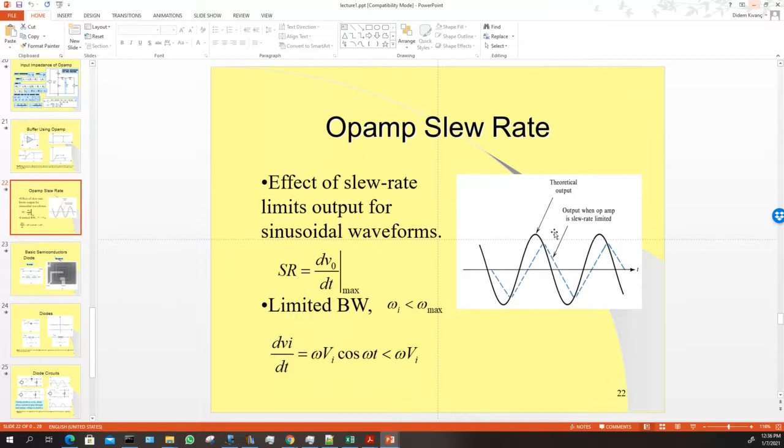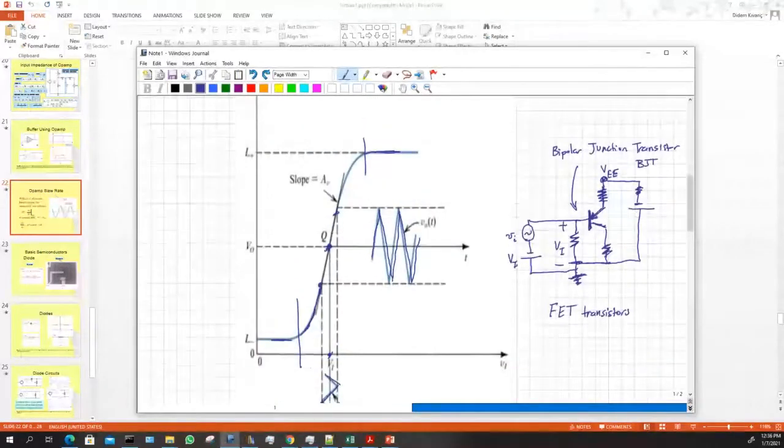So when you do, for instance, SPICE simulations of circuits, there'll be two different simulations that you do. One is for steady state. That's basically what we showed with the input-output of the amplifier. When the input is this voltage, the output should be this voltage. I'm applying this cosine, and I should see at the output this other cosine, a steady state analysis.